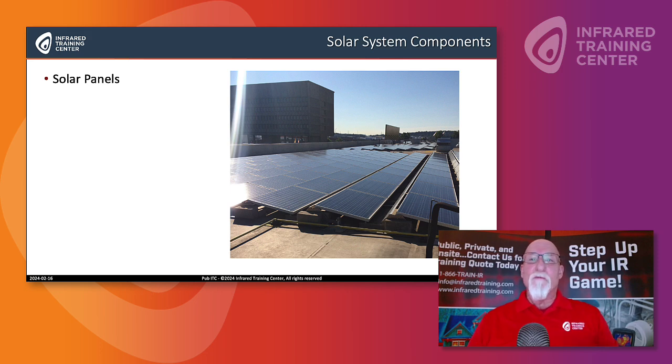So first of all, in our minds we need to be saying to ourselves, what type of panel is it? Who's the manufacturer of the panel? Not all panels are the same, or act the same. Also, what is the sun acquisition onto the panels? It's important that the panels are somewhat directed towards the sun, not down towards the deck. And so are there any obstructions that are blocking the panel?